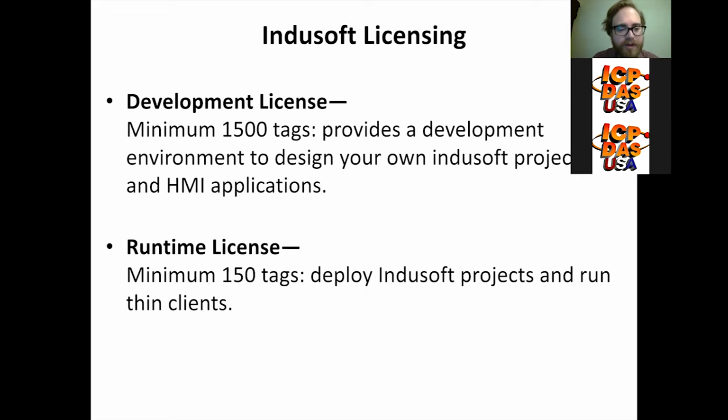You deploy these projects onto a runtime server, which will be the heart of your control system. Now, there are different runtime editions of Indusoft, which vary according to what you need. The full runtime license can be deployed on a Windows server, or a Windows PC running 7, 8, or 10 OSs, or Windows Embedded Standard versions 7 and 8.